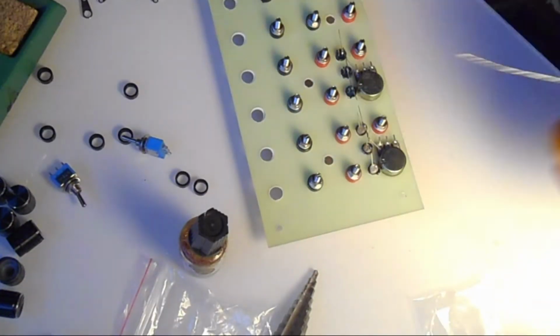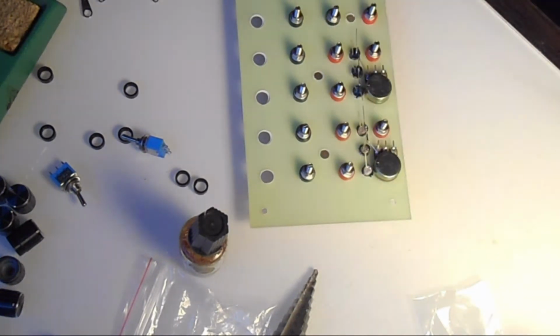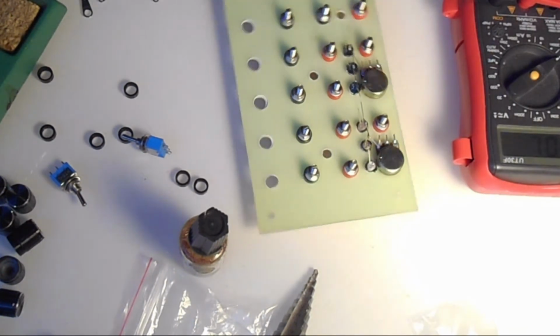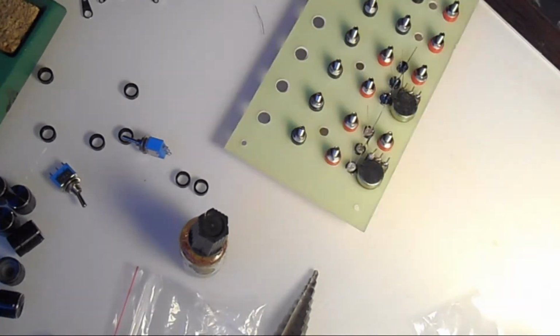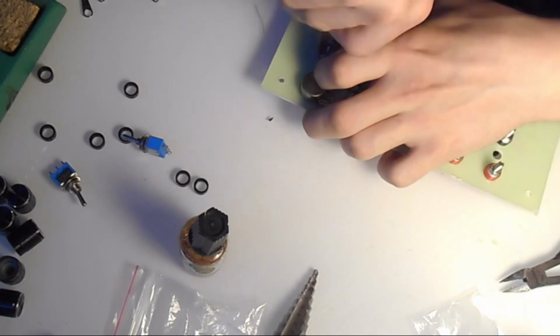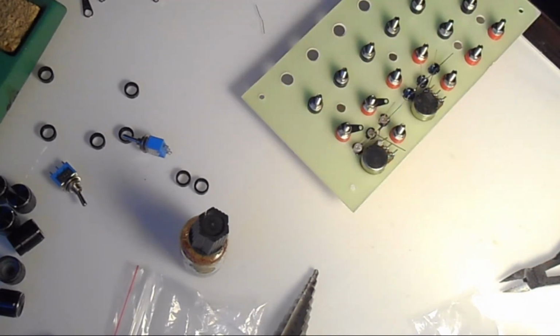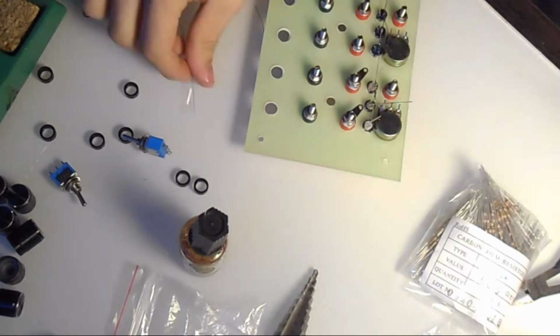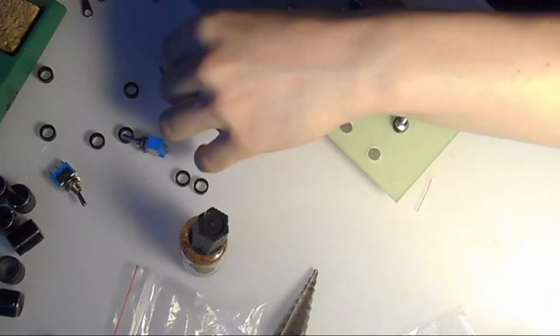Then I made all the connections planned to be done on the faceplate. The LED grounds and output amount potentiometer grounds are all connected into one large bus, which later will be wired to the PCB. I also installed the output impedances and the LED resistors for comparator outputs. Had no place for that on the board.